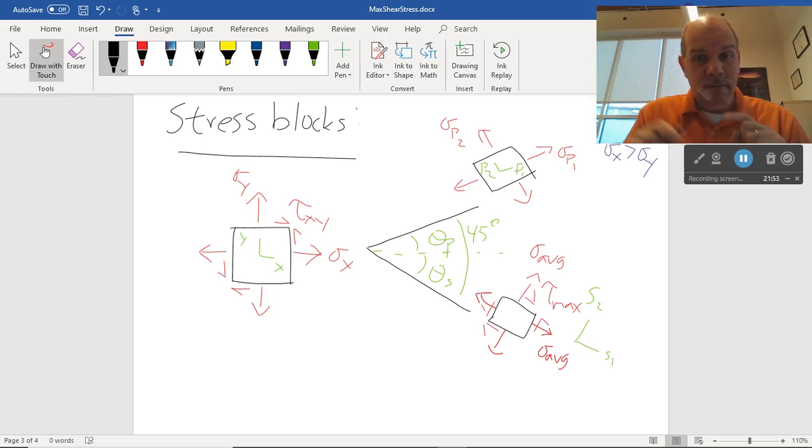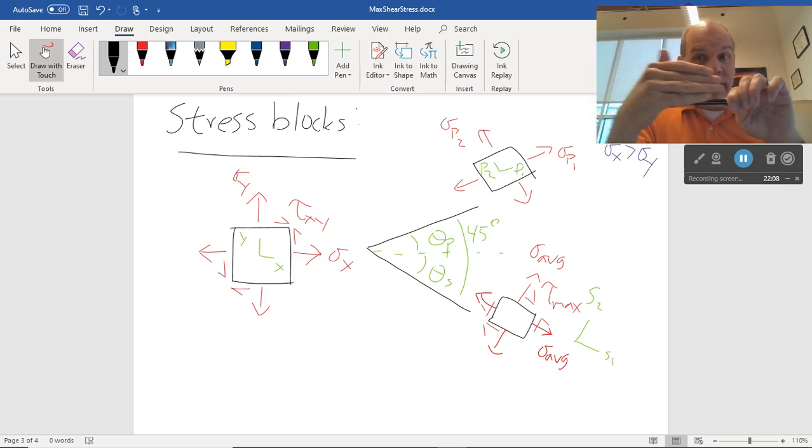One more thing, right? Notice how the axial stresses are equal when we have maximum shear stress. So if I have a state of pure shear, I just take and twist my little stylus here, right? I have no axial stress in this coordinate system where my x-axis is left to right on my screen, lined up with the stylus.